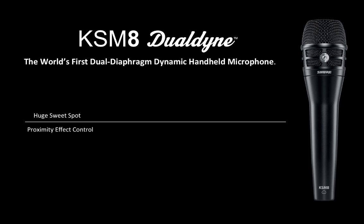I think it might be worth pointing out, just so that people are totally clear on what we mean by sweet spot, we are talking about that distance between your mouth and the microphone. Sometimes people think a sweet spot is like getting off to the side. It's still a cardioid pattern in terms of its angle of acceptance, so it shouldn't be taken to mean that. If I move way off to the side here, I'm sure everyone can hear the level difference versus when I'm right in front of the microphone. So again, we're talking about front to back, controlling proximity effects so that your low end stays consistent. That's what we mean by the sweet spot.